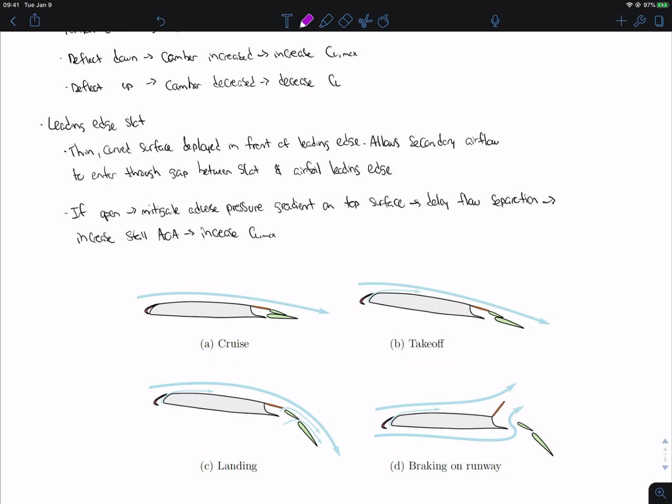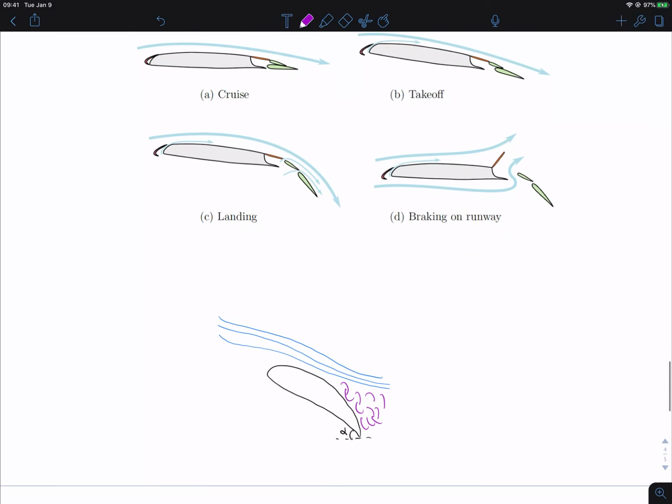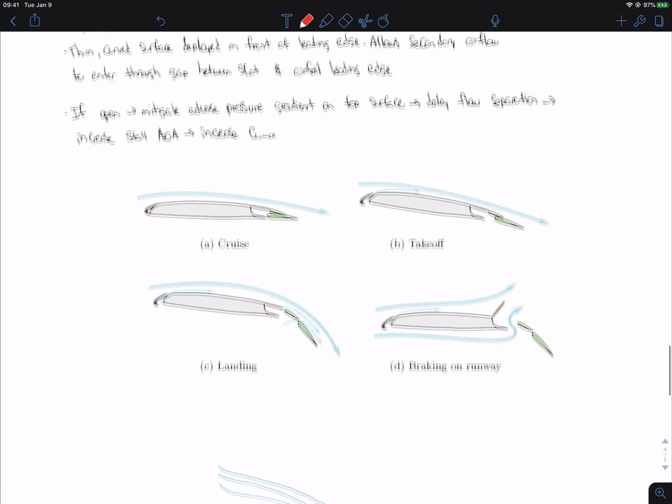However, once we're increasing our angle of attack, at some point we're going to increase this angle of attack too much, where the top flow is going to become detached from our airfoil. It's not going to be able to curve around as it should, like this in red. It's going to detach, and from that detachment of the airflow, we have what's called airflow separation.